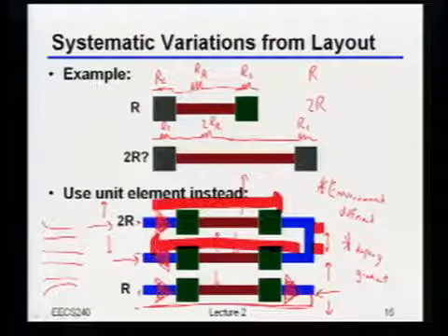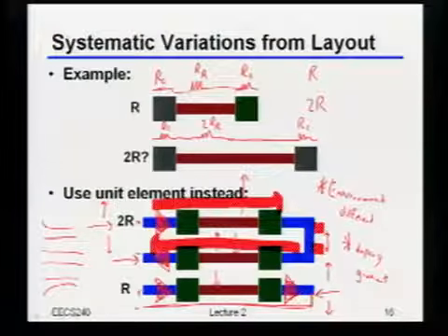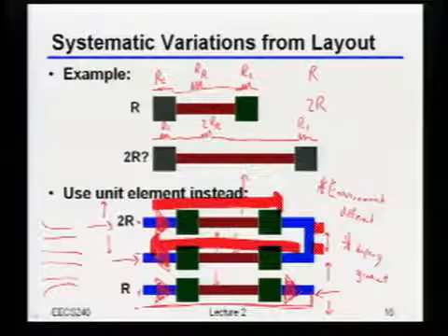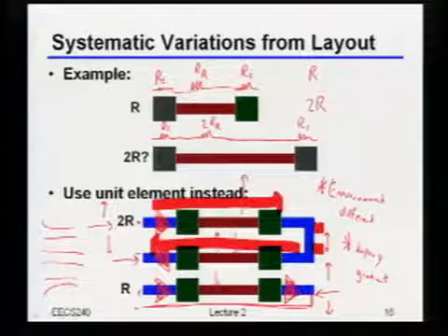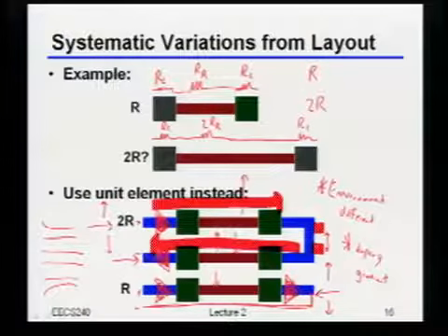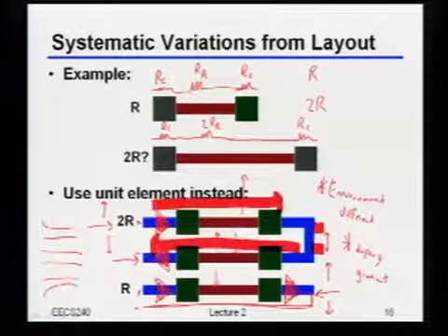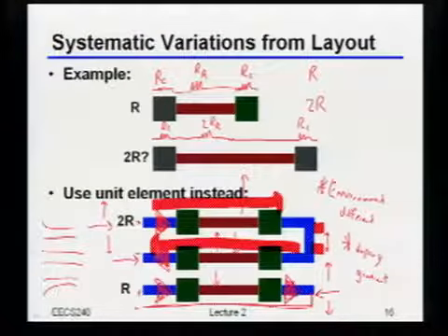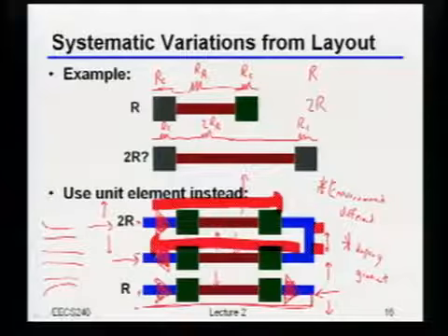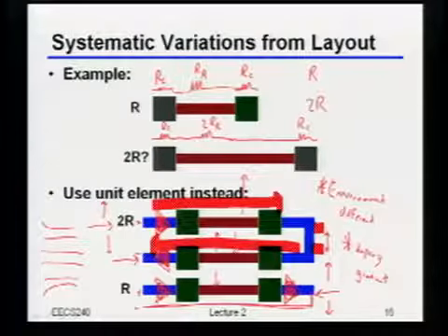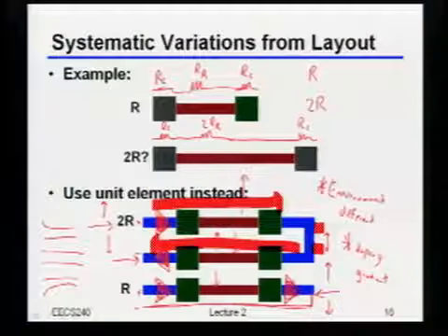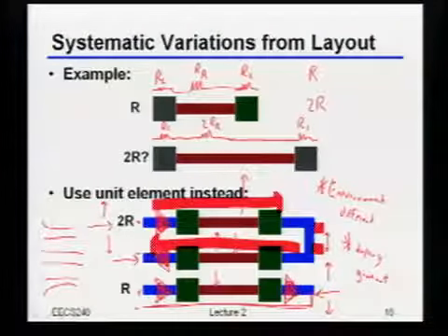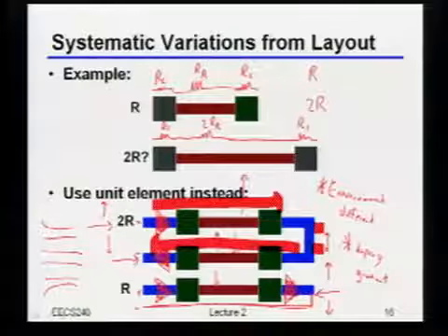You're absolutely right. Now, by the way, this is again a processing thing. The reason why the direction may actually matter is because when they do the doping, that's generally at an angle, and it's at one unique angle for the entire chip. So things that go one way are not exactly the same as things that go the other way. Now, poly resistors, usually that's not too big of a deal. But all these tricks that we're talking about for layout to make sure that things really match are just as important for MOSFETs, and in fact, sometimes even more.